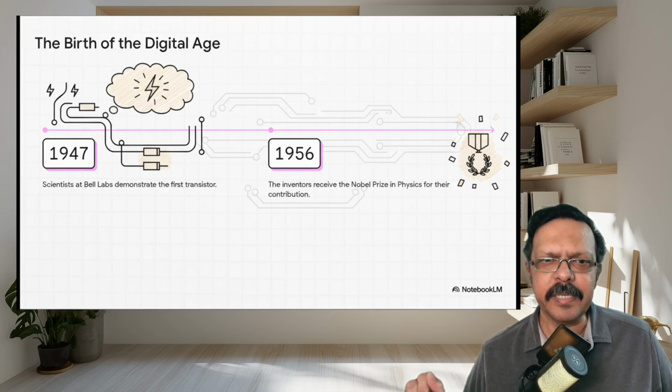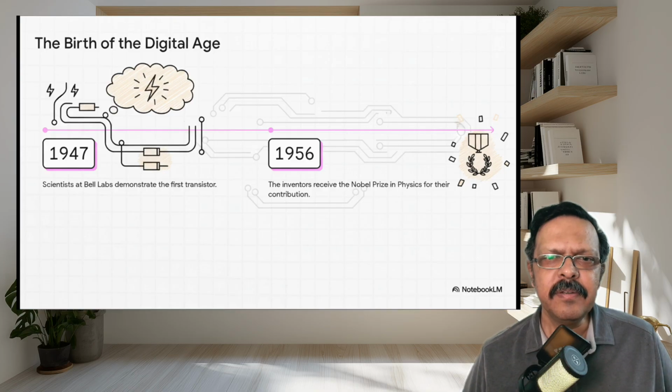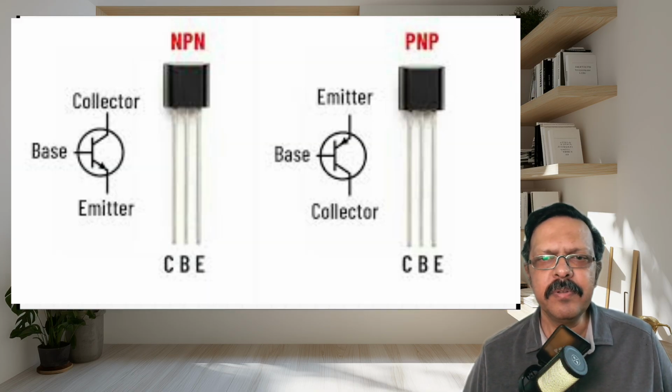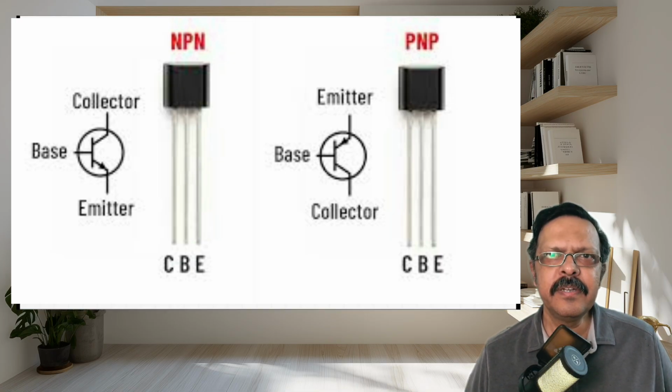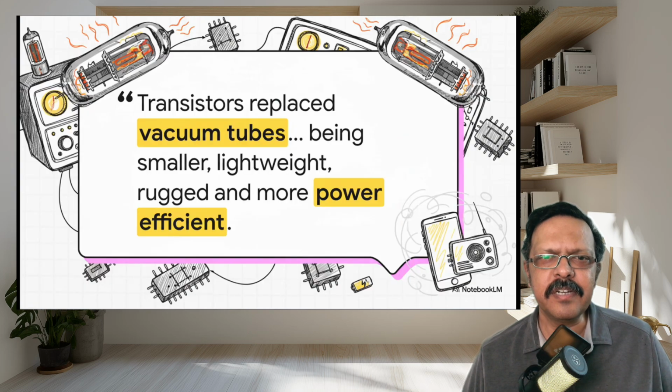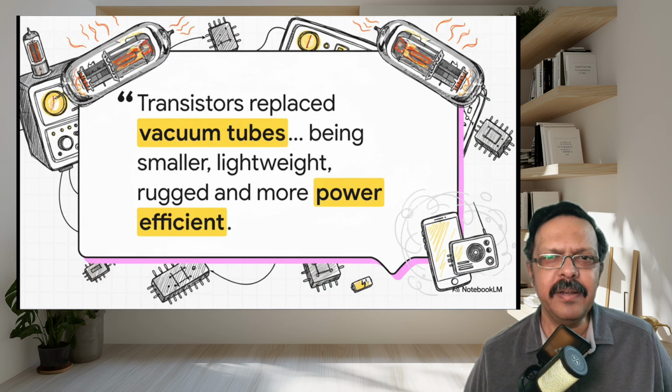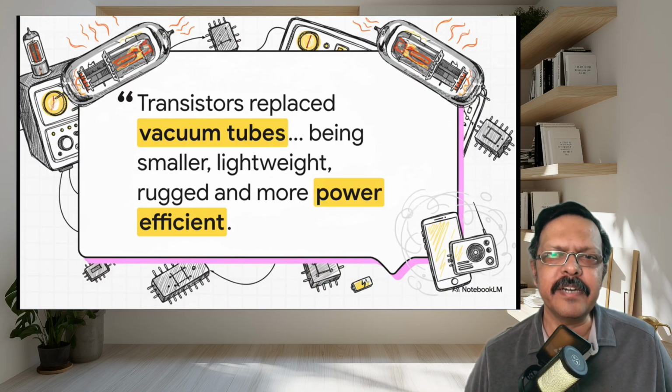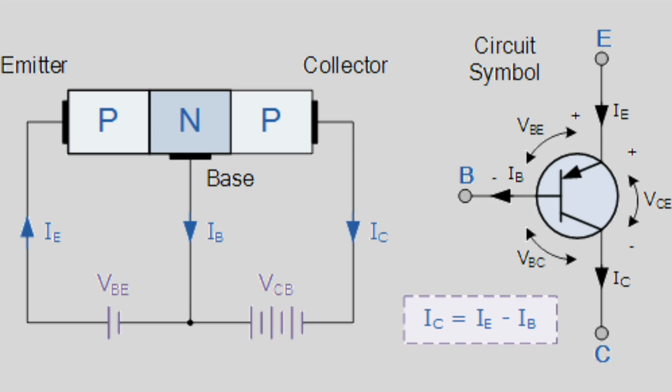There are two major types, the NPN transistor, where we have the N-type, then the P-type, and then the N-type, all put together. Then we have the PNP transistor, where we have the P-type, N-type, then P-type again. In other words, a transistor is basically two PN junctions back to back. This structure gives it something the diode does not have, a controllable middle layer that allows us to regulate current. So that middle layer is the base and it's the secret to everything that follows.